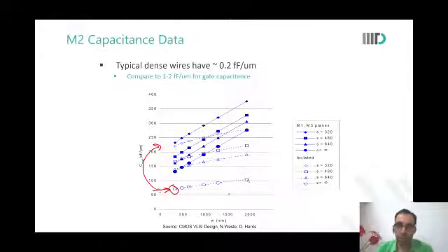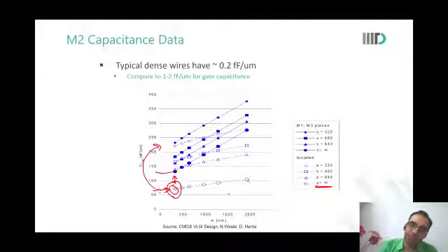Now, when there was only a single wire, because the spacing is infinity, and I put in the metal 1 and metal 3 planes, the capacitance increased from 60 to 130, more than doubled. But in a dense wire configuration, when I put the metal 1 and the metal 3 planes, the capacitance increased from 220 to only 230. Insignificant change.